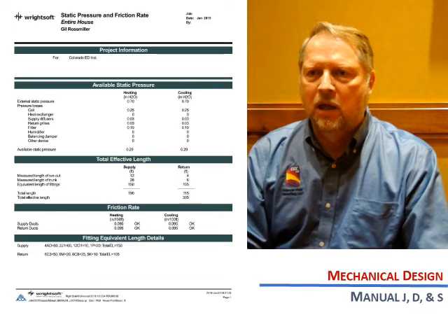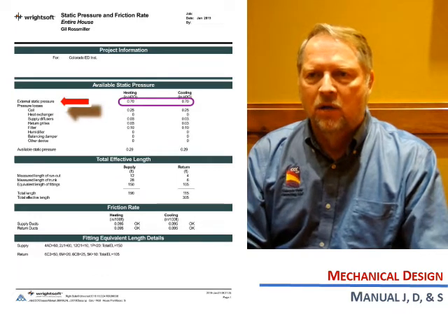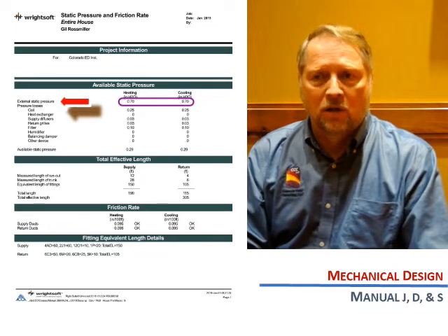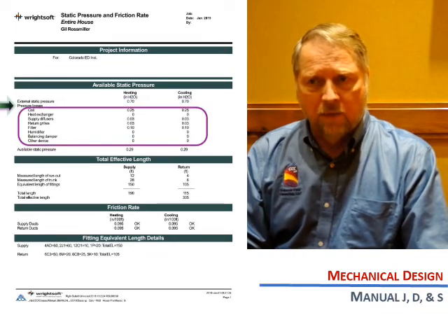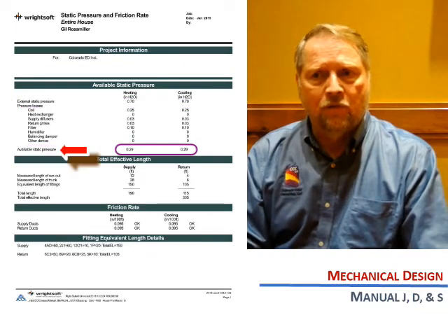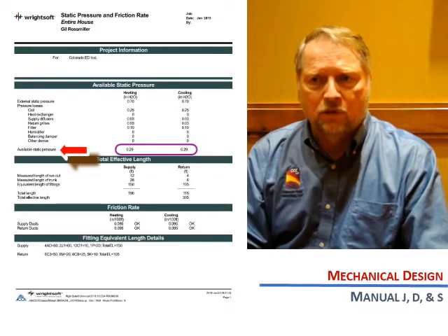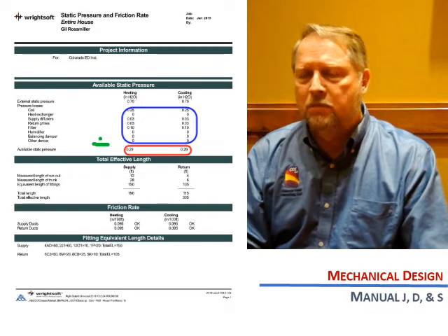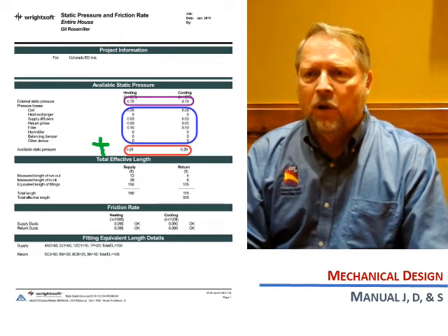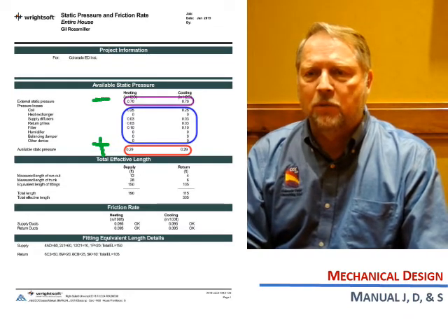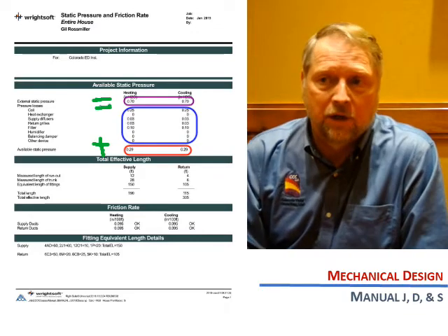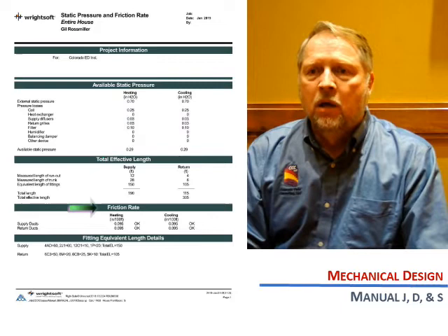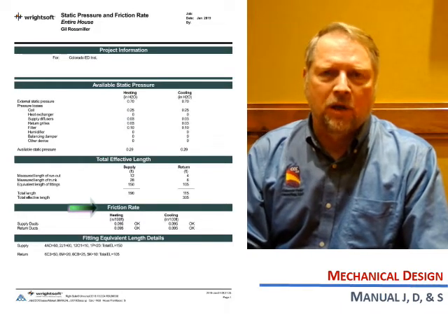Manual D, then, is the design of our ductwork. We're going to look at things like our external static pressure, then pressure losses, and then finally our available static pressure. This group of numbers should be equal in a balanced equation. If you add up our pressure losses with the available static pressure, you should equal the external static pressure if everything's added up right. We need to look then at our friction rate. That's probably the biggest deal.